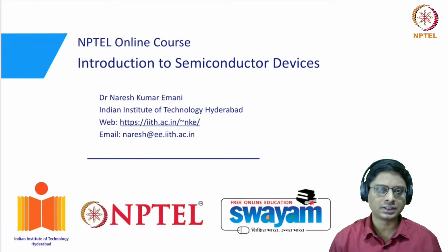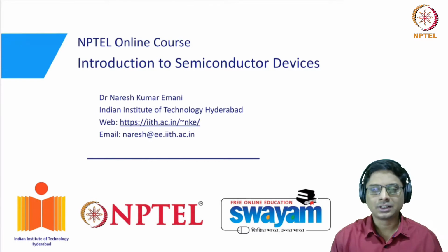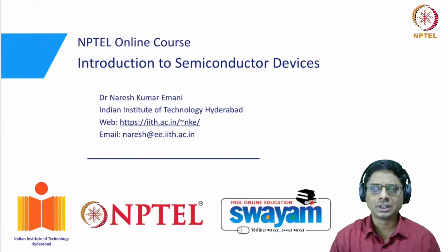So we have studied the electrostatics of a MOS capacitor in great depth, and in the lateral direction from source to the drain, it is essentially two PN diodes which are back to back, right? So we have seen how there is a barrier formed across a channel, because of which current will not conduct, and that barrier can be changed by applying a gate voltage. So this is the essential physics of the MOSFET.